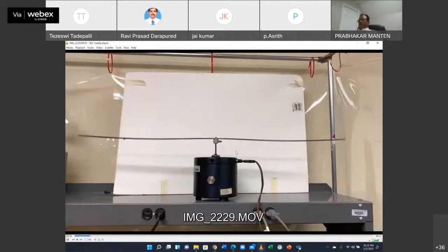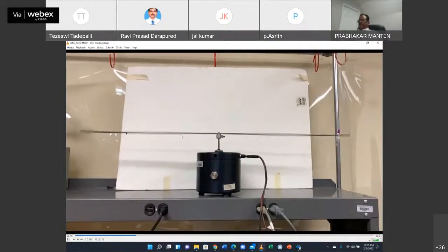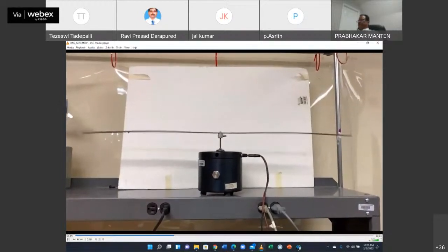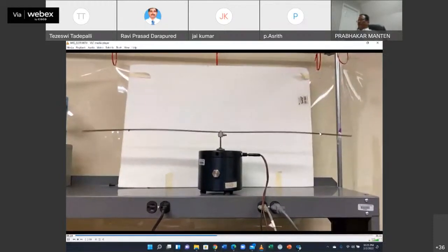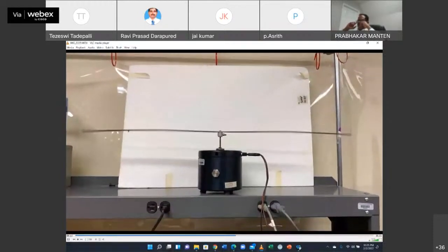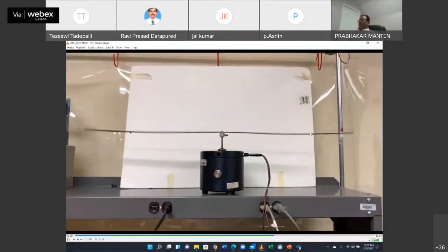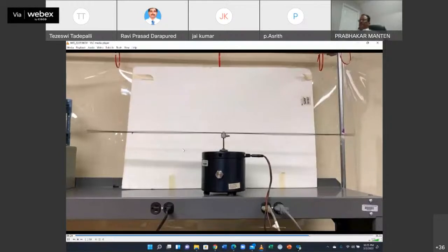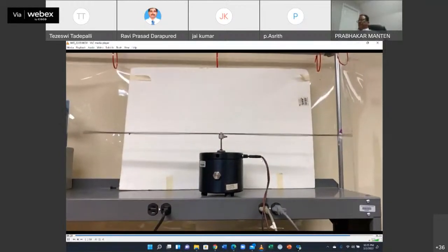You see, what do you see over here? What is this point? The rest is moving here and here, almost static. You can capture that exactly with the stroboscope light. We did it, but the stroboscope frequency and the camera were somehow mismatched. We could not freeze frame it, but actually with the students, we shut all the lights and we froze the frame. So up to 3 modes. The next was the third mode, which we captured too.